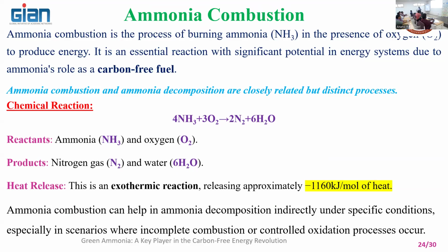So ammonia combustion is going to be useful for an internal combustion engine. If you want to completely eliminate petrol, diesel, gas fuel, LPG or CNG, and completely eliminate the carbon dioxide emissions, the only option is to replace the conventional liquid or gaseous fuel with ammonia. But ammonia has a decent calorific value of about 50% of that of diesel or petrol, maybe around 40%. So we need to increase the size of the fuel tank.